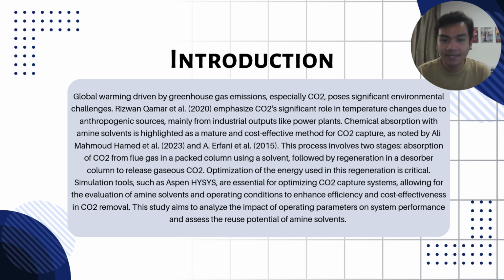CO2 removal. This research addresses the critical need to identify the best amine solvent for CO2 capture through comprehensive Aspen HYSYS simulation studies by systematically evaluating different amine solvents and their optimal operating conditions. This work contributes to the development of more efficient and cost-effective CO2 capture technologies, supporting global efforts to reduce greenhouse gas emissions and combat climate change. Therefore, this study aims to evaluate the effects of varying operating parameters on system performance and to analyze the regeneration efficiency and reuse potential of the amine solvent in the stripper.